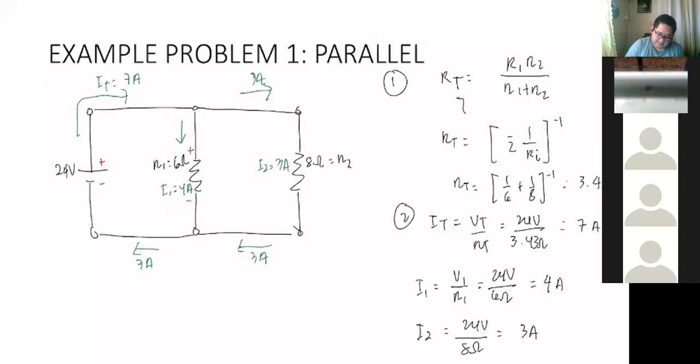Next is identify natin yung mga voltage value natin. Okay? Ano yung value ng sa A natin? Voltage natin. Okay? So starting natin is 0 volts. Pag akyat dito, voltage left tayo. So 24 volts. Sa C, ilan yung voltage natin?